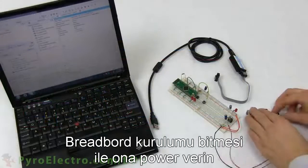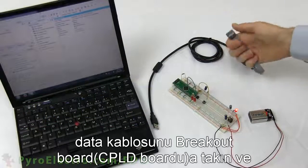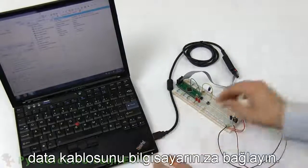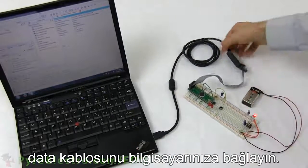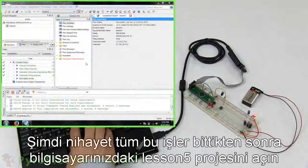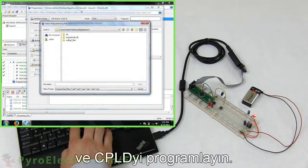And with the hardware built on our breadboard, let's power it up, connect the JTAG cable to the breakout board, and connect the JTAG cable to your computer. Now finally, after all that work, open up the Lesson 5 project on your computer and program the CPLD.